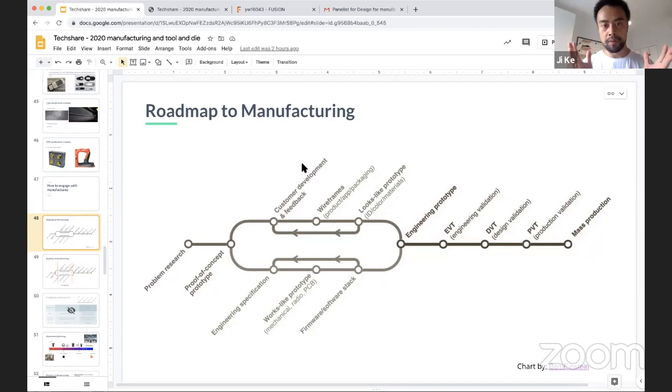When you choose injection molding, you absolutely have to design and optimize for the mold. Like I said before, ultimately you're not the one who designed the mold, the injection molding factory is, and they can add on costs when something doesn't make sense. From the simplest things, a device with a draft angle versus one with no draft angle is a completely different cost, and you have to design it in.